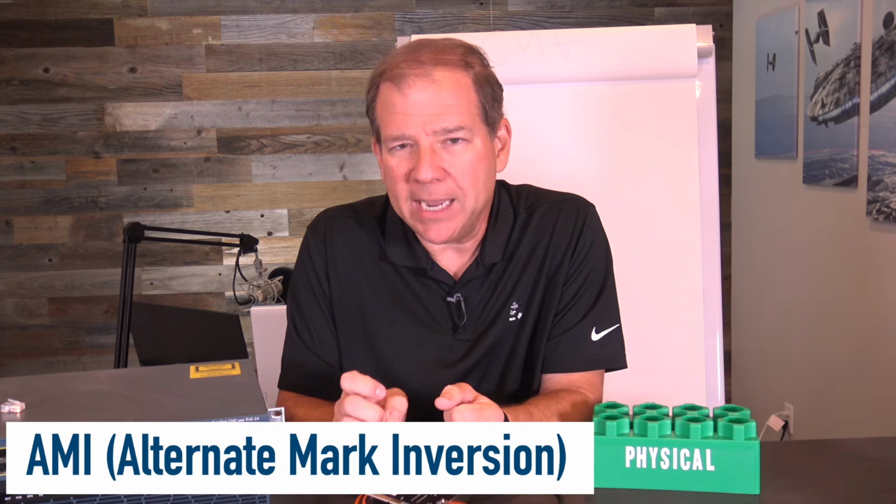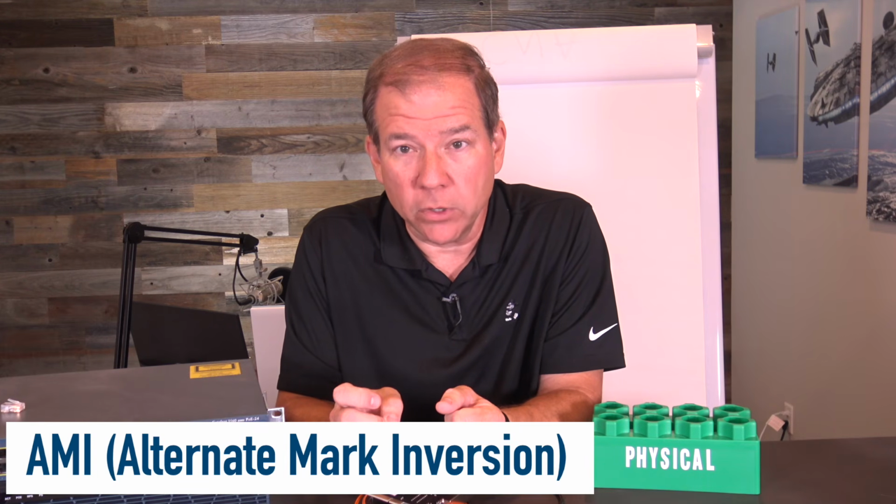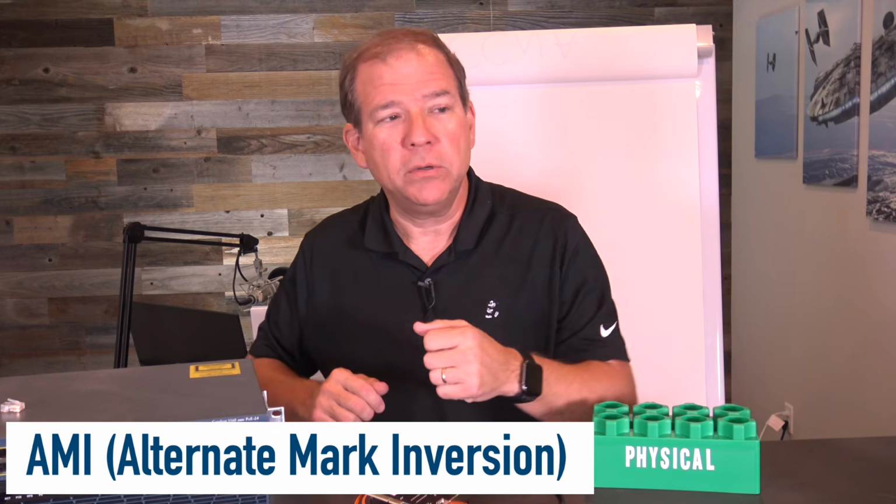There are a variety of examples out there, but let's take a look at just one to give you a better sense. Let's consider a way of encoding data called AMI, alternate mark inversion. Now, AMI goes by the thesis that it's best to have an average of 0 volts on the wire. That's a good electrical characteristic. So what we're going to do is represent a binary 1 as the presence of voltage. One time it's going to be positive, the next time it's going to be negative. So on average over time, we have an average of 0 volts on the wire.